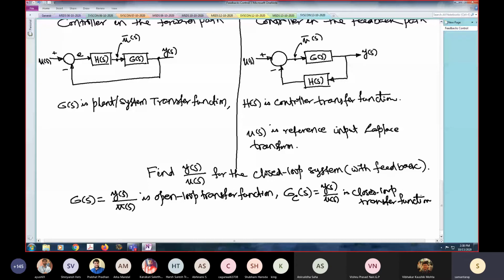Maybe my spring mass damper system had force as input, but after implementing the control system, the input to my closed loop system is the desired displacement. So my input has changed. Outputs have not changed. With that changed input, I need to find the transfer function of the entire system, including the controller. That is what is called closed loop transfer function.